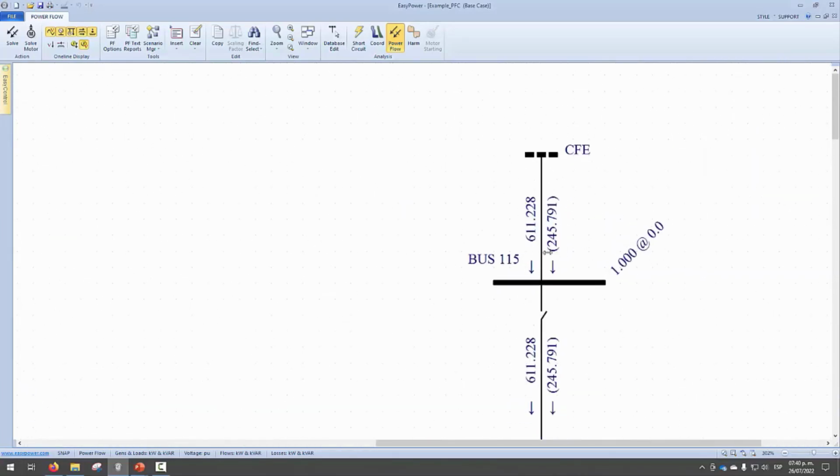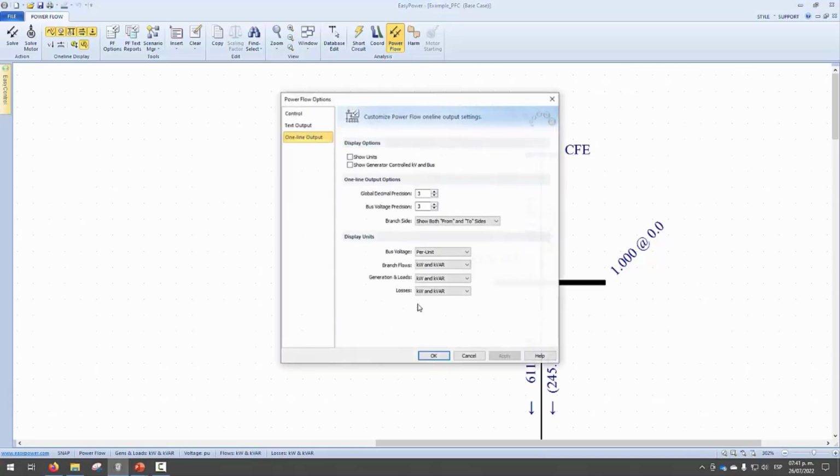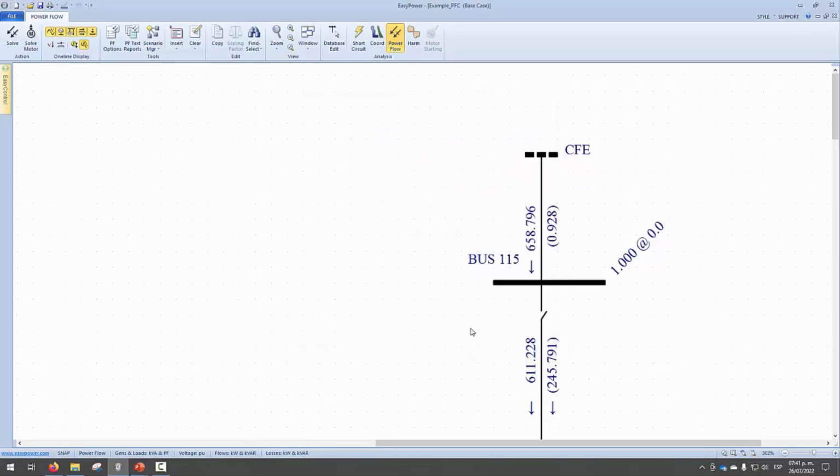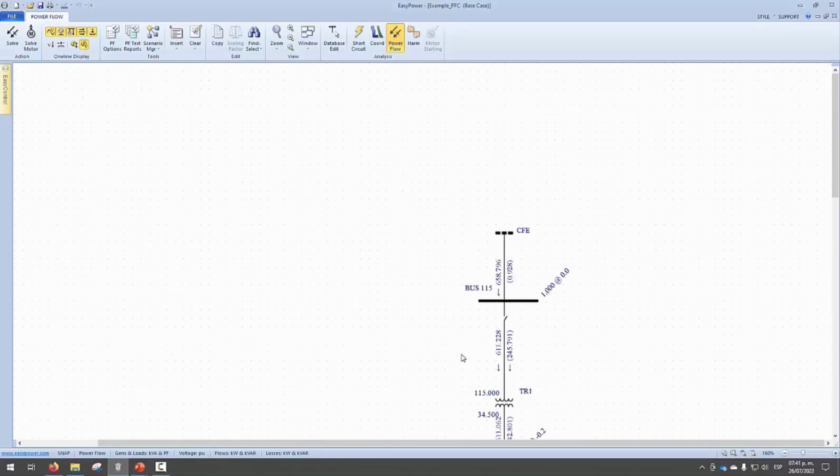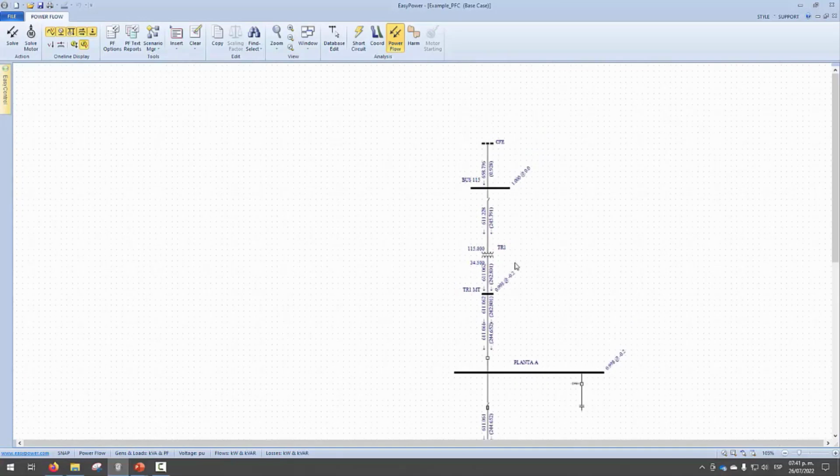I still have a very large reactive power requirement, but how's the power factor? It's acceptable. It's up to 92, so it's all right. But then the facility manager says, no, I want a unity power factor. You've got to install something on the middle voltage side.